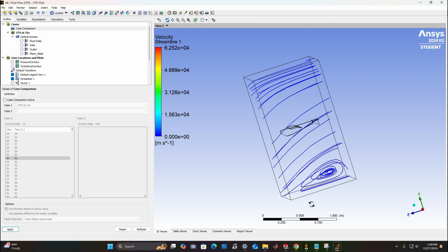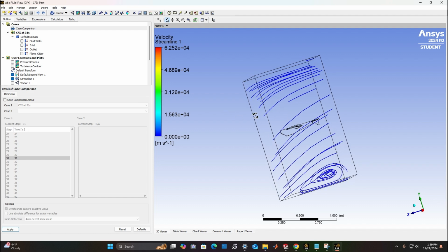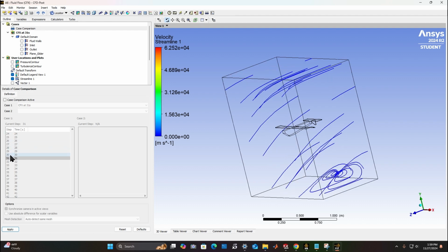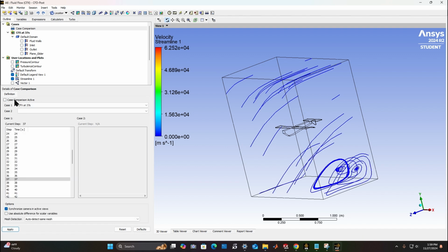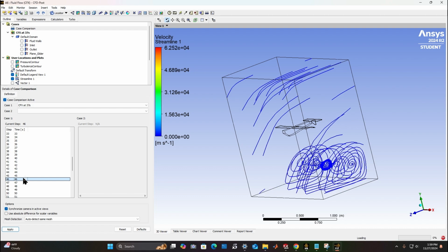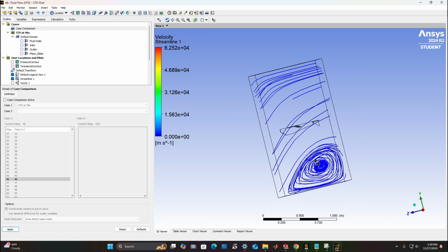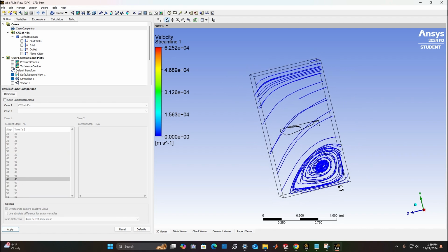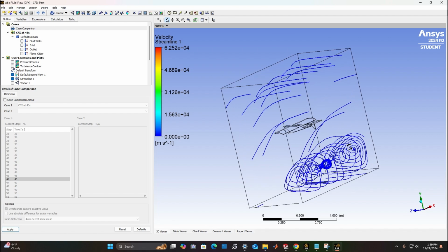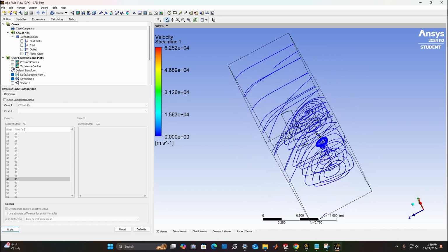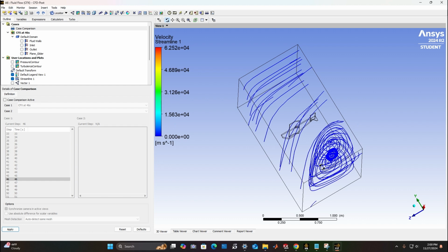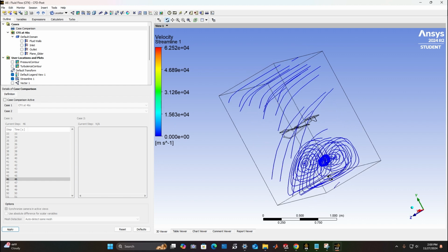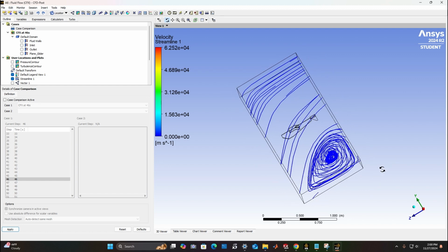This is because there's no way for the pressure to escape on the outside, even though there is a vertical velocity heading towards it. And as you can see, as time progresses, this effect magnifies and it starts a spiraling vortex. So on future analyses, we're going to want to change this from a free slip wall to something that can have pressure escape.